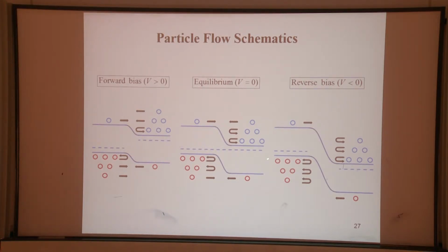All right. Also, for the holes, the P side has a lot of holes, right? Actually, this diagram is for electron energy. So you need to see the positive charge holes the other way. The upper one means holes with lower energy, and the bottom one is a hole with higher energy. Only those holes with higher energy will diffuse toward the N side. But it will be counteracted by the electron diffusion in the other direction. And the holes with low energy cannot overcome the barrier, so they are blocked by the p-n junction. So this is the equilibrium condition.